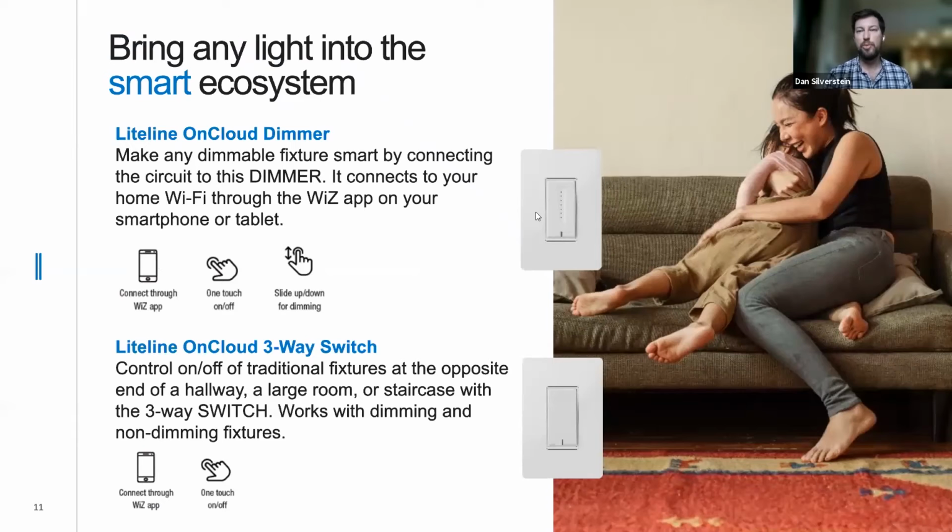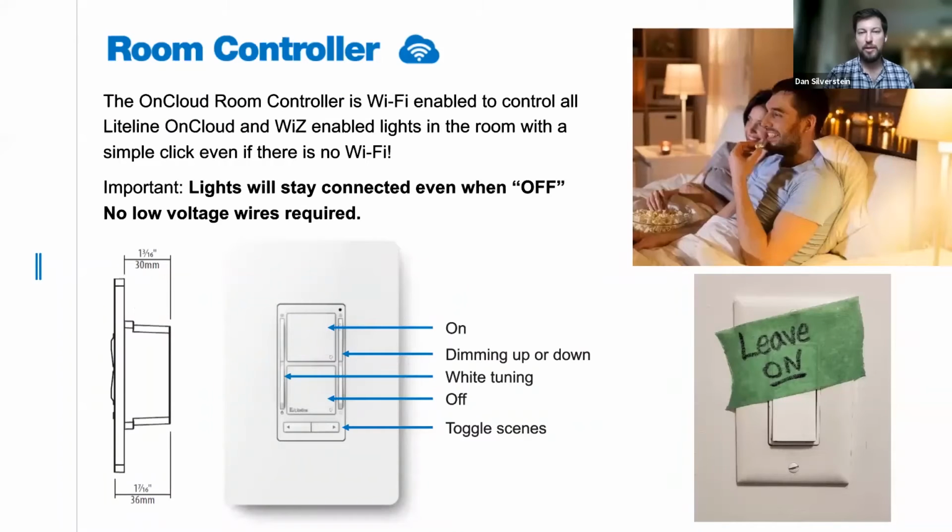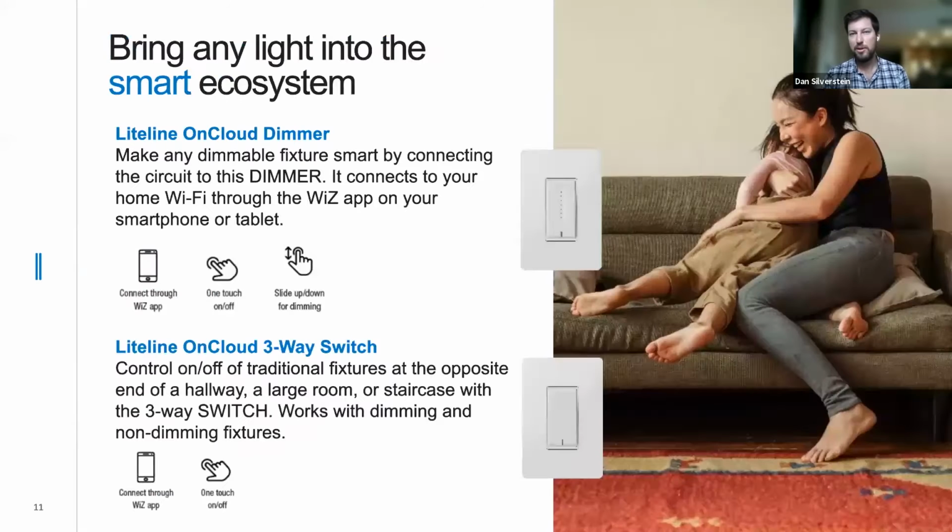So if you have a three-way application, what you do is you take your load, whether it's your KLICK or a traditional downlight or a traditional halogen fixture kind of thing, you wire it up to this dimmer the same way you would wire up a traditional dimmer in a single pole application. And then for your three-way, you take the room controller, and the room controller controls the dimmer.